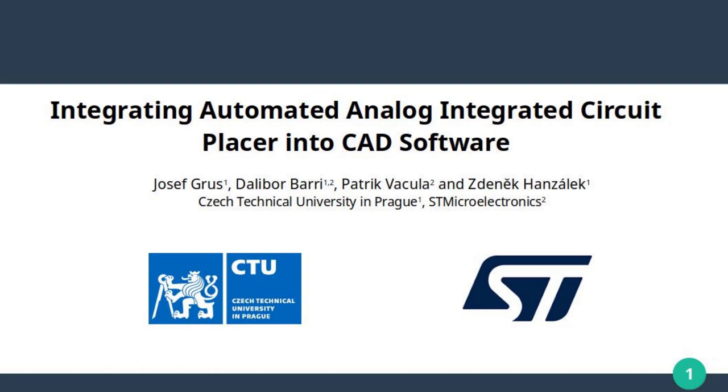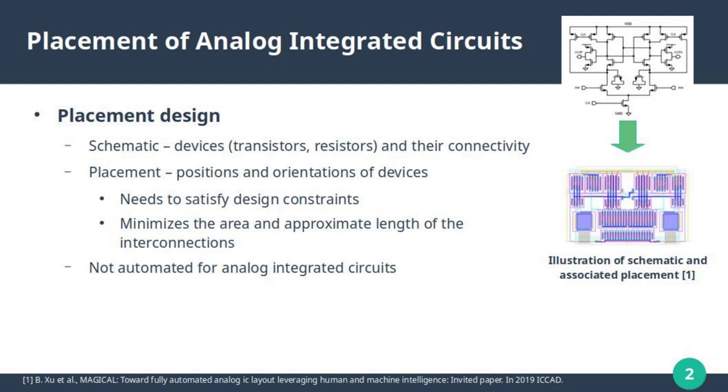We would like to present our work on integrating an automated analog integrated circuit placer into computer-aided design software. Placement design is a step in the overall circuit design when the schematic is transformed into placement. A schematic, such as in the top right corner, describes the used devices such as transistors and resistors and their interconnectivity, while the placement assigns to each device its position and orientation.